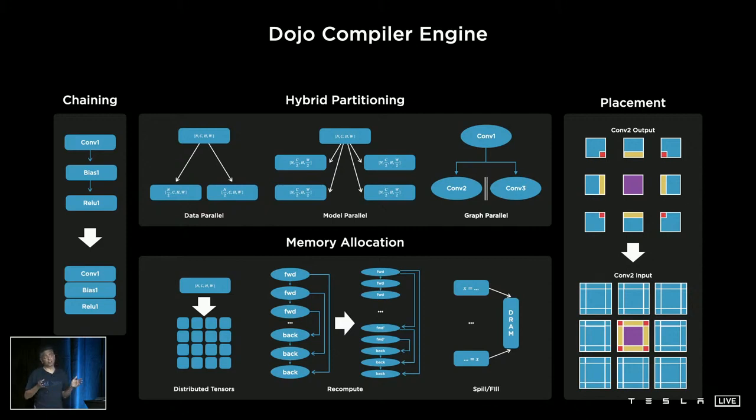One thing, because of the high bandwidth nature of the fabric out here, is that model parallelism could not have been extended to the same level as what we can. It was limited to chip boundaries. Now we can, because of our high bandwidth, extend it to training tiles and beyond. Thus, large networks can be efficiently mapped here at low batch sizes and extract utilization and new levels of performance. In addition, our compiler is capable of handling high-level dynamic control flows like loops, if then else, etc.